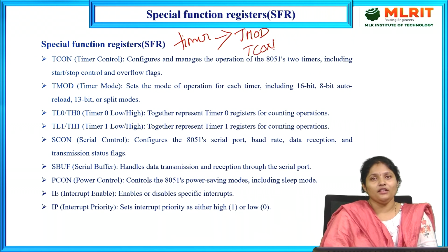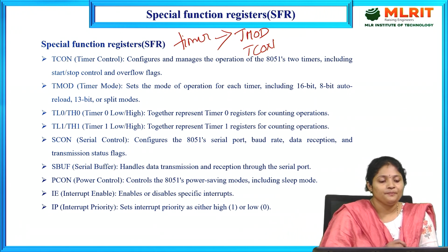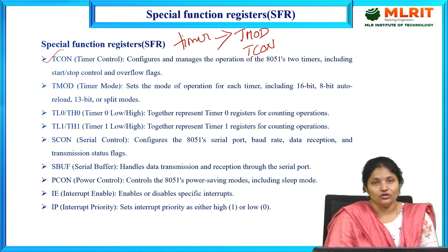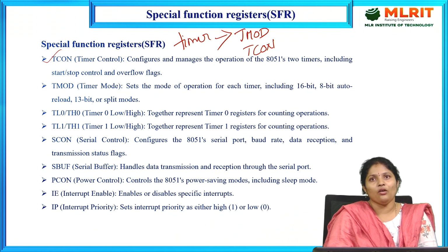TCON is the timer control: when to stop the timer, when to start the timer, which of the 2 timers needs to be started or turned off, and the 2 timer interrupts, TF1 and TF0. TCON configures and manages the operation of both 8051 timers, including start and stop control and overflow flags.